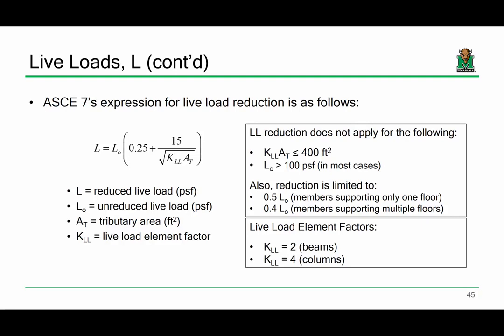Tributary area. I think for our purposes now, everybody should be pretty aware of that. If not, for now, that's basically just the area halfway over to the next adjacent beam. I'm actually playing a little fast and loose with that for the folks that aren't in concrete design, and there's a reason for that. We actually don't talk about beams in here until near the end of the semester, whereas in concrete design, we're going to talk about beams immediately. So for now, it's not really that big of a deal, and it won't become that big of a deal until like April. So I'm just going to sort of play fast and loose with that.